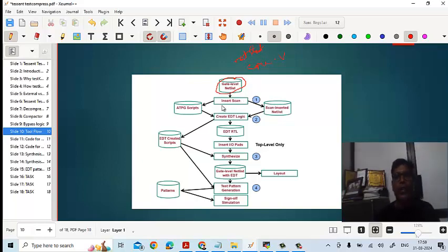You take this and you run insert scan. For insert scan, we are doing a scan insertion through the scan.do file. Once we do this, 2 files get generated out of it. One will be the ATPG script file, the other one is the scan inserted netlist. Both files get generated after you run the scan.do file in Tessent.